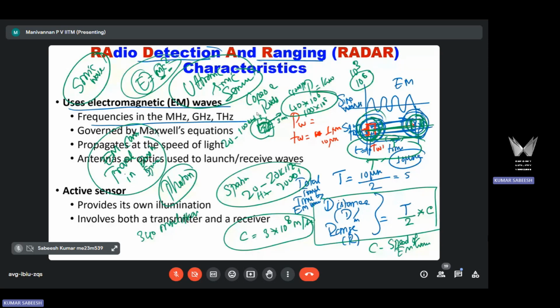If the sound goes and hits an object and is reflected back, that will be sensed by the same ultrasonic sensor. Same principle. It sends a sound signal and it is reflected. It knows the time. Total time divided by 2 is the time for the sound wave to travel one way. Then multiply t divided by 2 by 340, if it is sea level, since this is the speed of sound. That is the distance to the object. That's how ultrasonic sensors work in car reversing, all those things.